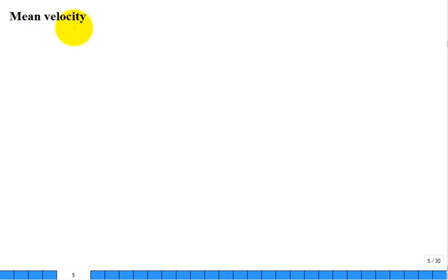All right, once I have the description of the velocity profile, u is equal to u max times 1 minus r over cap R, squared, how do I calculate that mean velocity? Well, what's the criteria for the mean velocity? Because we're going to get to the mean temperature, and when we get to the mean temperature, we're going to scratch our head and say, well, what was the concept that we used for the mean velocity?